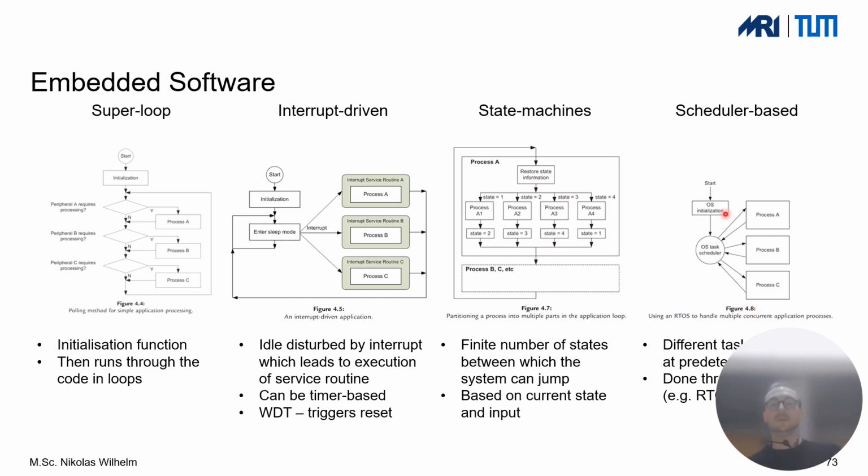So this will then be something nice for a scheduler-based architecture where you have different measurements at very predefined times that should be executed at this time. And for the rest of the time, you maybe want the system to save a lot of energy, so not be running through the main loop 20,000 times per second, but just be resting and not doing anything, but then every day you turn on, do the required stuff, and then you turn off again. So that's a scheduler-based system.